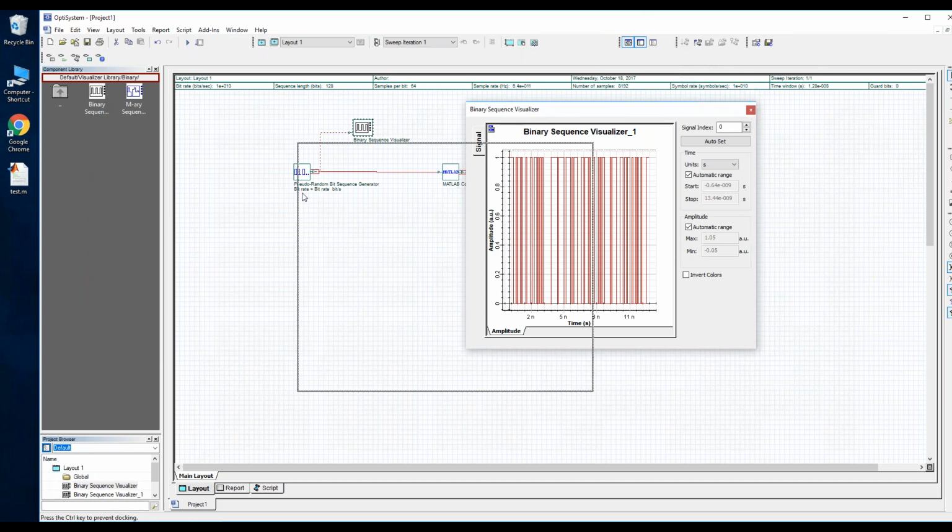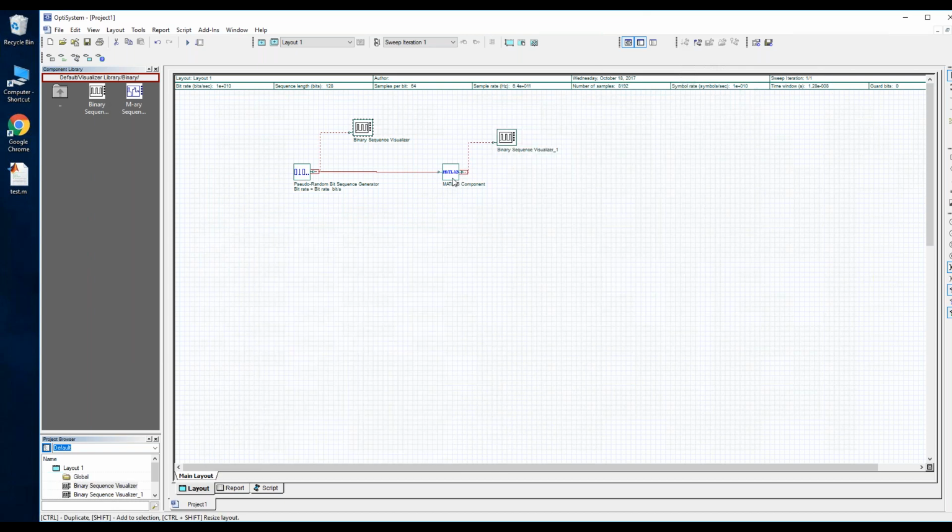There are certain things that you have to take care of. You have to make sure that you match the size of the sequences, right? I couldn't add extra bits to that bit sequence because then the system might be confused about how that's being interpreted. And the same goes for the optical and electrical signals, where you can't just add more data to that signal. You have to only modify it, or at least make it usable by the OptiSystem framework.